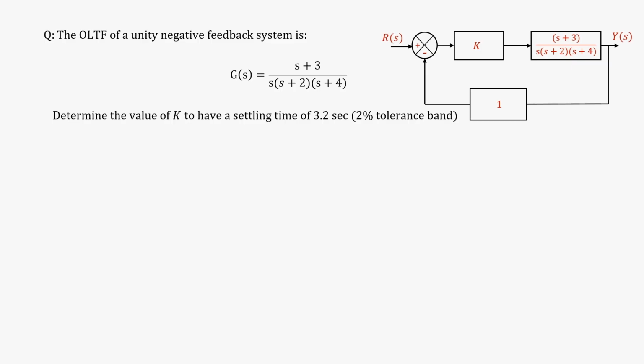So, the steps will be almost similar. However, the system has changed, the specification value has also changed. Okay. So, let us look at it again, how to solve this. Again the steps will be similar. Okay. So, again first let us find out the desired pole location.